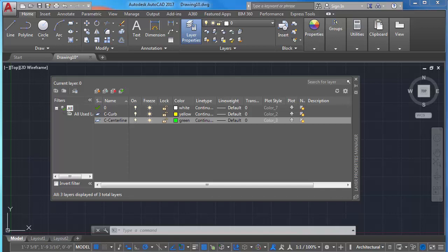We can also associate a particular line type with a layer, such that anything we draw on that layer will have that line type of either dashed lines, solid lines, or other types of lines. To do that, in your command bar, type linetype or LT.